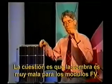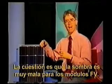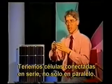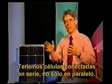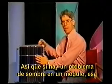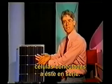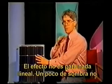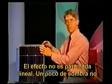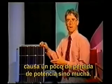One of the points that we're trying to get at here is that shading is extremely bad for photovoltaic modules. We have cells connected in series, not just parallel. So if there's a problem with some sort of shading on a module, that shading restricts the output of all the other cells connected in series with it. The effect is very nonlinear. A little bit of shading doesn't cause a little bit of power loss. A little bit of shading causes a lot of power loss.